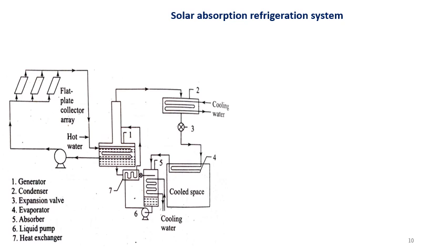In essence, cooling is accomplished as the generator of the absorption cooler is supplied with heat by fluid pumped from the collector storage system or from auxiliary. Okay.